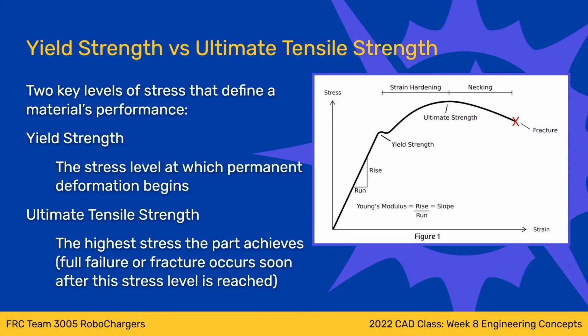So when I talk about being able to go online and look up 1045 steel and get a single number that quantifies this part of the material property, that is generally true, but that data sheet will apply to a specific heat treat. Chances are, if you just go look it up, you'll find whatever the most common heat treat for 1045 is. I don't know what it is off the top of my head, but that's something to understand: these numbers can change depending on how the material is heat treated. In the context of FRC, this really doesn't matter, so I'm leaving heat treat out of the rest of this presentation. But that's just a quick note.